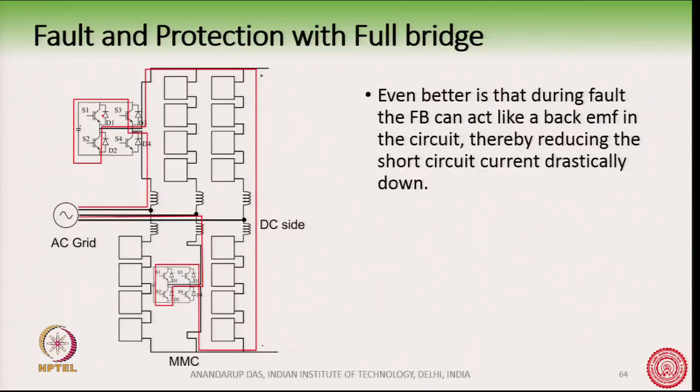So, if there is a fault, the natural tendency is to shut off the transistors, so that you can protect the converter. So, that is the natural way of thinking. However, it may be better under some circumstances to actually run the converter during fault condition.